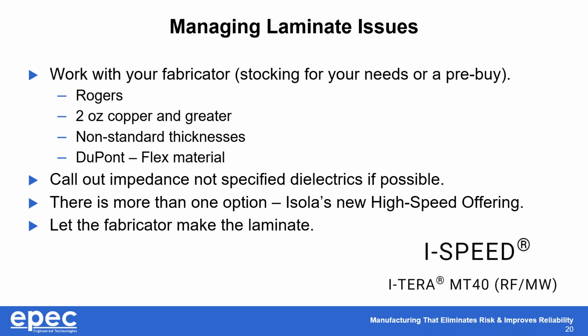One, we can stock it for you. If you say, listen, I'm going to use this specific Rogers, and it's a 20 sheet minimum order, but I'm going to use it over the year, we'll buy it. Most fabricators will buy it and put it on the shelf. Otherwise, you may be 8 to 12 weeks if they're out, right?